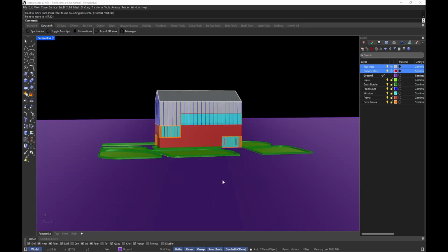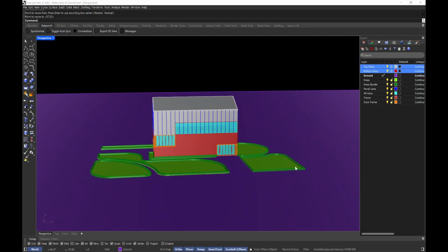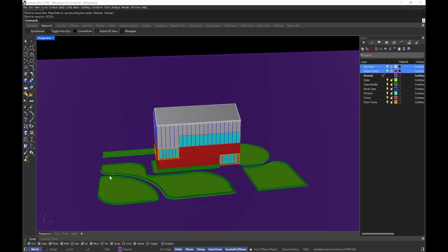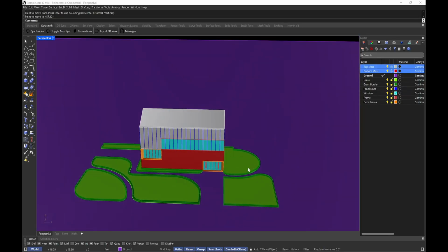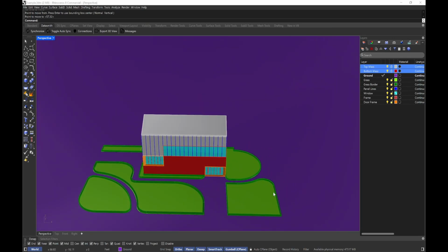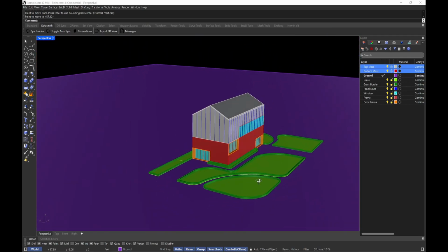Okay, like I said, I just wanted to fast forward and do some extra landscaping edge elements. You saw me do these two pieces here, but I did the exact same method over here. I planned it out, drew it out, did tangents, did fillets, did the curve boolean command, split it with the ground, extruded the borders, and then offset them. So the exact same thing that you saw me do earlier.